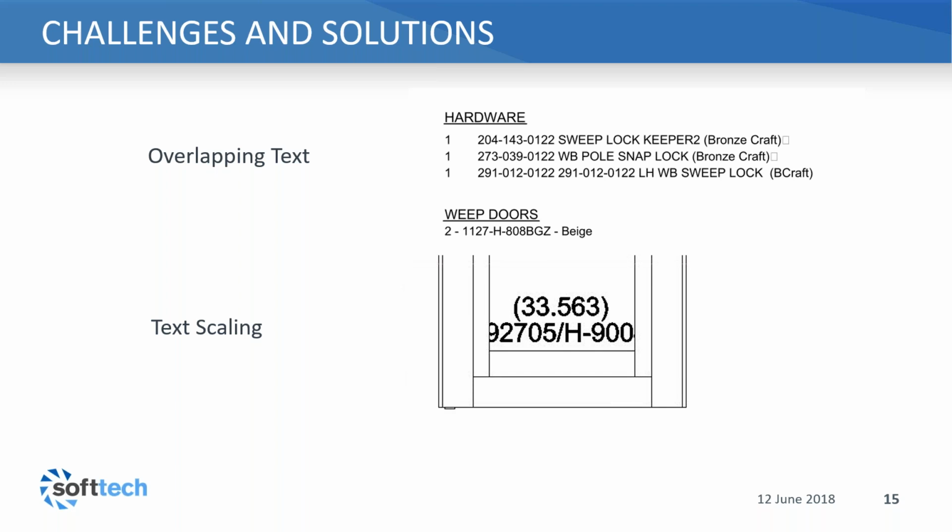If we determine it is not going to fit, then we have 2 ways of dealing with it. We can reduce the width factor of that text, something I've always done in the past. But one thing to bear in mind is that once you start reducing width factors beyond, say, 0.5, the text becomes unreadable, and it's just no good. So we calculate what the width factor would need to be to fit in that space. If it goes below 0.5, then we can reduce the text height and recalculate the width factor again.